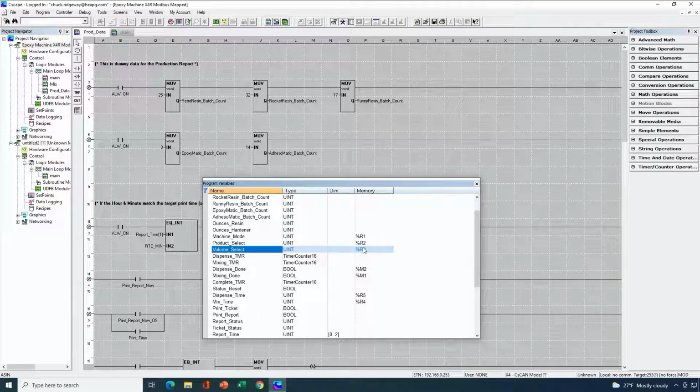You always want to go consecutive where possible so that it's as efficient as possible for the external device to grab the data in as few messages as possible. So you don't want to have them mapped all over the place from a Modbus perspective. You want them in really as consecutive a memory locations as possible.